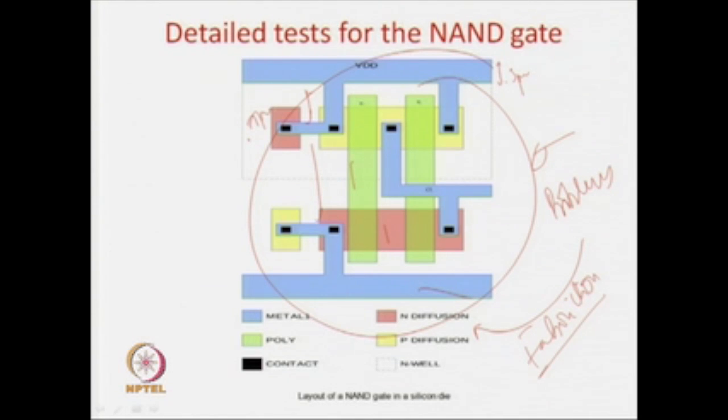So, what is the difference between verification and test? In verification, what do you verify? Say I wanted to design an adder. I verify whether I have really written code that actually implements the adder. So, I verify that it is functionally what I intended to design. If there is any failure in the verification phase, then you can be sure that it happened because of the designer's mistake.